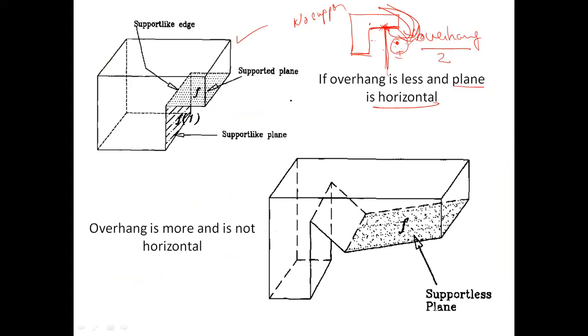In the same way, when the build time decreases, the surface which is going to be in contact, suppose this surface doesn't require support, in that case this surface is not going to degrade. Because wherever the support structure is attached, when you remove the support structure there will be degradation on the surface. You have just seen it with an example. So if no support is needed, quality will automatically become better.